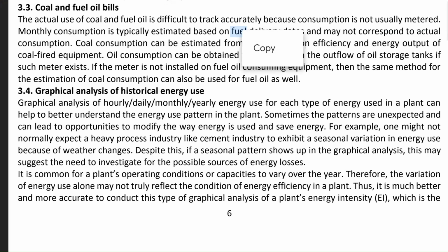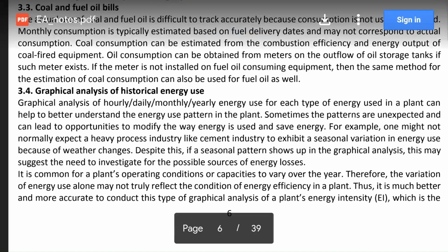What else is to be taken into consideration is the combustion efficiency of the coal. When we talk of coal efficiency or combustion efficiency, we mean that if we are using good quality coal, then it will have good combustion, and as the quality goes down, the combustion efficiency also goes down. For example, good quality coals like anthracite and bituminous have good combustion efficiency. If we are using inferior quality, for example peat, lignite, etc., it will have less combustion efficiency. Similarly, it will be charged.